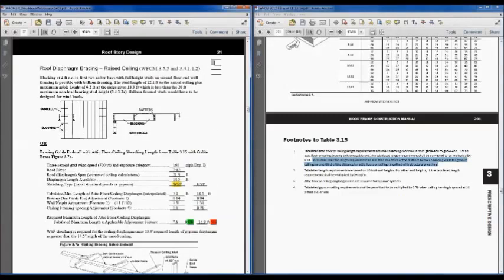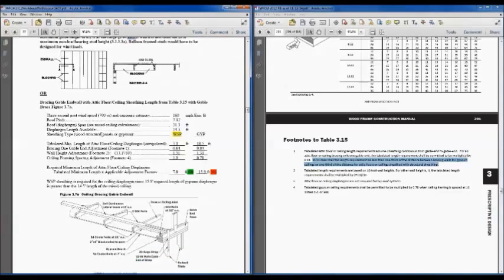Now let's jump to the raised ceiling provision. So again, you could block it at the roof system. If we do that, though, we would then potentially have to balloon frame our studs on that end of the wall, and then we've got to look at our wall system in a little bit with that balloon framing and make sure we can balloon 18 feet with wall studs. So if we do that, that means some balloon framing, some additional detailing, or we can go again back to table